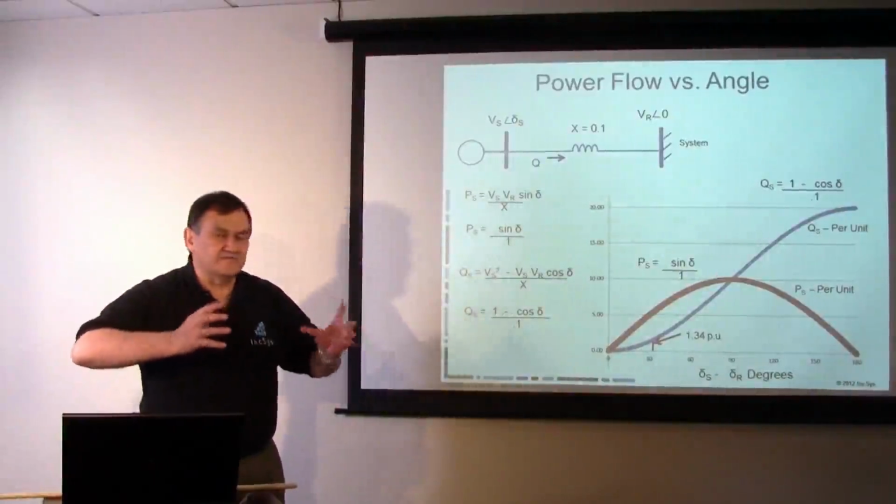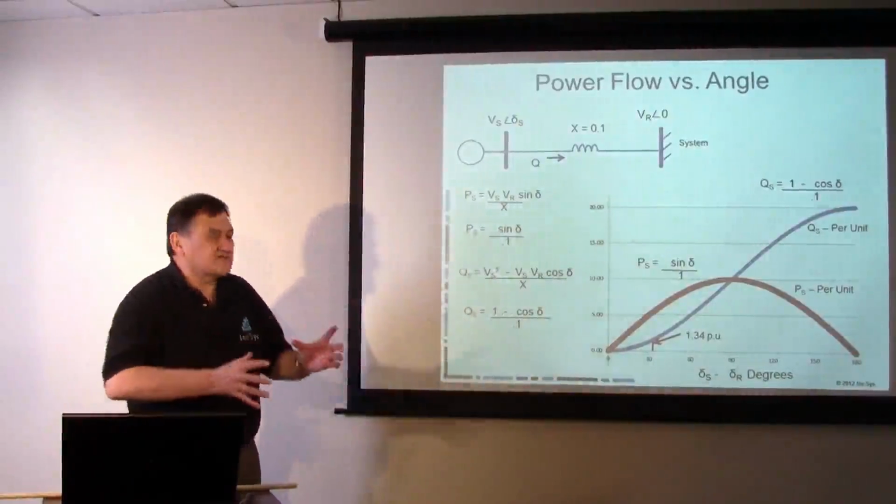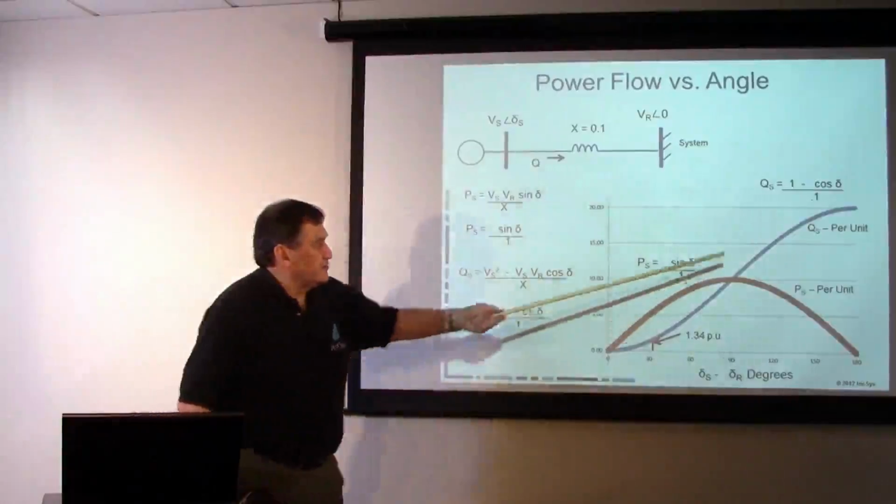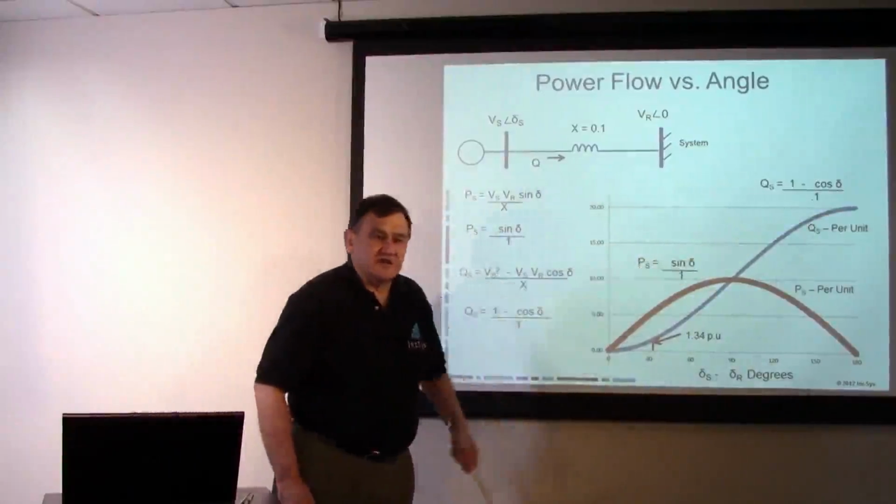And this is really important for you to understand: reactive power flow is drawing current, and that current will trip relays. Even though there are no faults on the system, as my rotors oscillate, I can have lines tripping out of service because we have huge reactive power flows and currents.